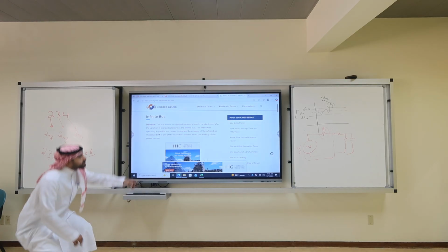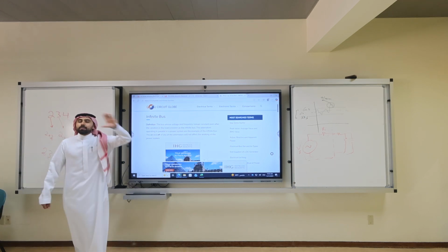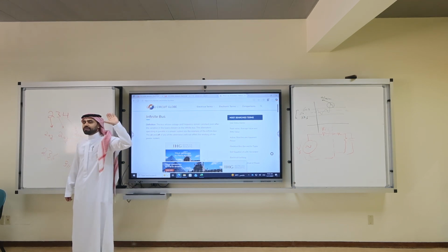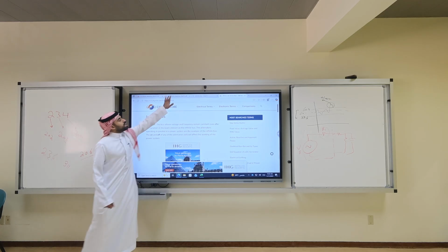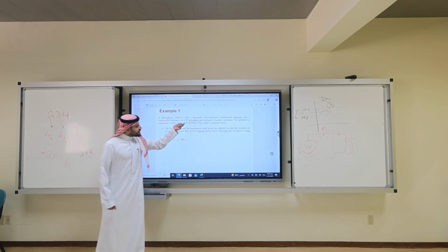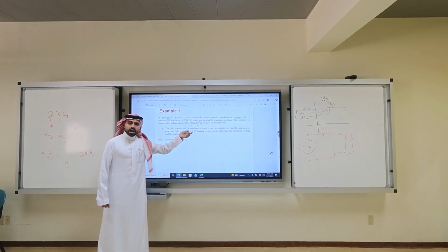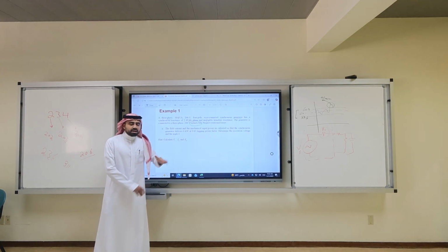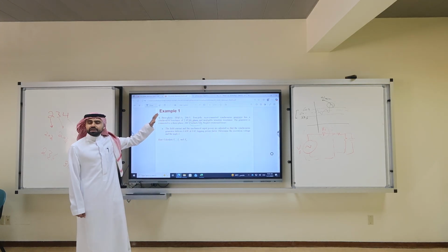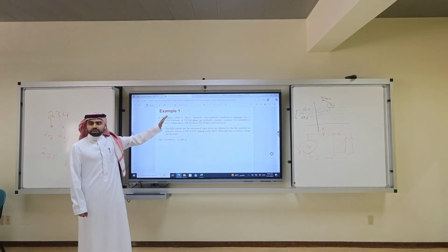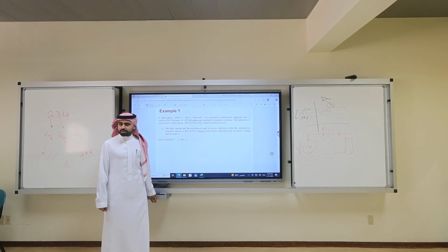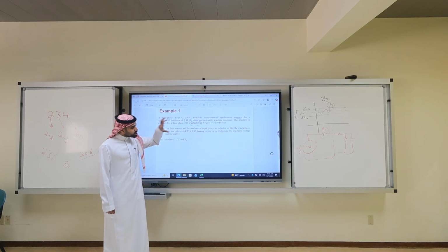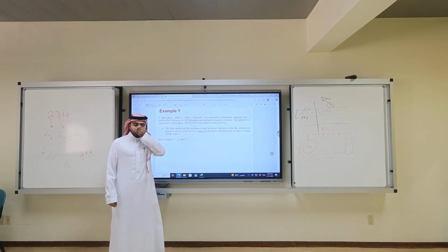It's a bus that has fixed voltage and fixed frequency. So what does that mean? It means the load is at 208 at 60 Hertz regardless of whatever is happening. The load is connected to the synchronous generator, and the terminal voltage is 208, fixed.